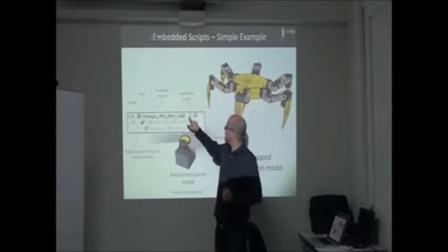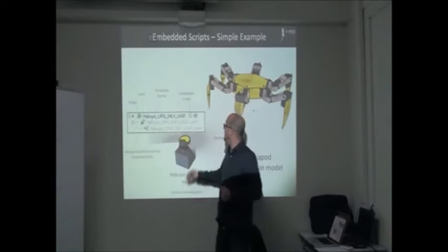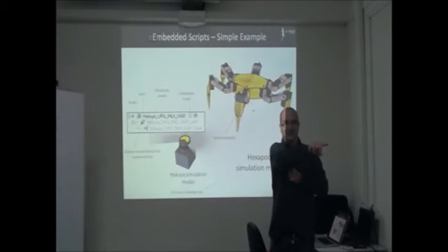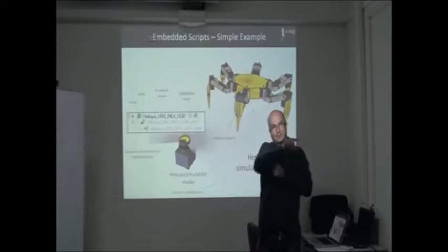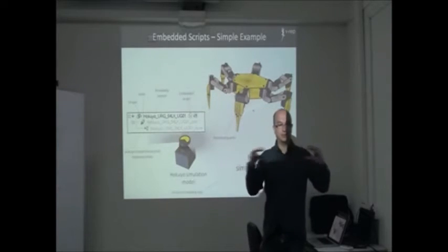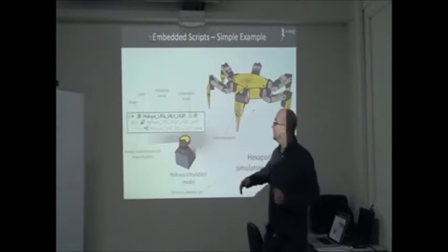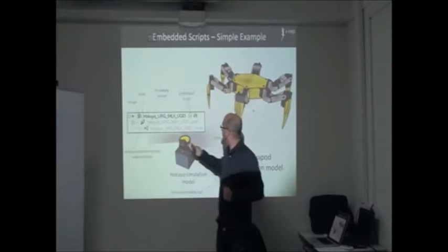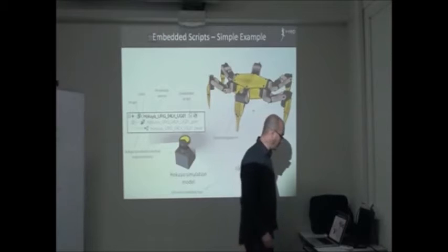No, not yet, because we need to have the control script. The control script is attached to this object. And what is it doing? It is managing: I want to read the laser. Now I want to rotate the motor by 1 degree, read again, rotate 1 degree, read again, etc. And put all those distance data into an array, and make that available for all the scripts to read. Also, I want to manage whether I display the laser or not, this kind of thing. Everything is coded into this embedded script.